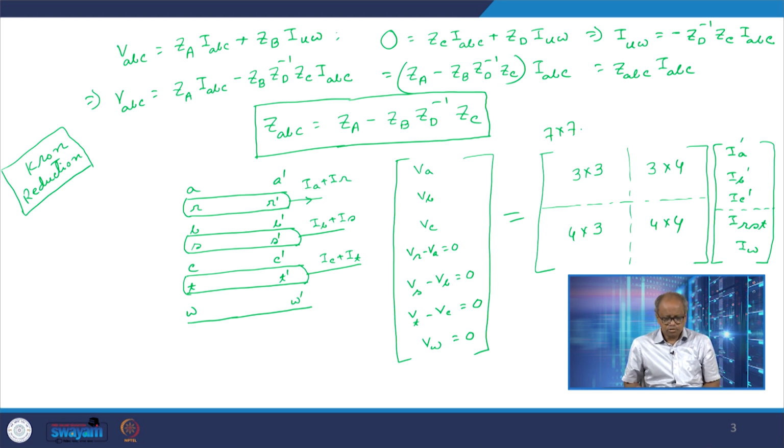After we partition this, same. So by combining the techniques of considering the bundle conductor or the case of 1 or 2 ground conductors, we can now analyze any case for any number of conductors connected in any fashion. Of course, here we have considered only the case of 2 bundle conductors per phase.